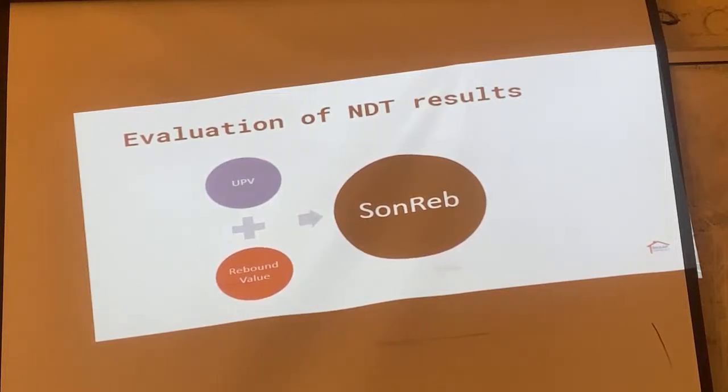We've spoken about correlation. Now, we'll also use another correlation curve between the estimated compressive strength gotten from UPV and that of the rebound value. Now we correlate them together, and then we use regression analysis to determine a relationship between the UPV result, rebound value, and the correlation value. So all of these big jargons I just mentioned all end up in an Excel sheet.